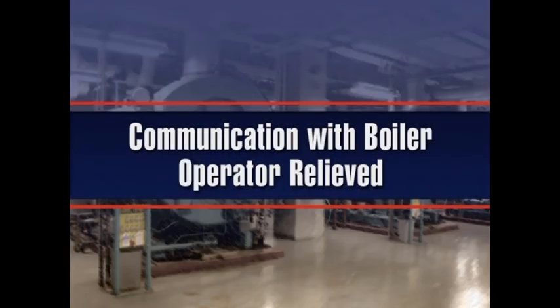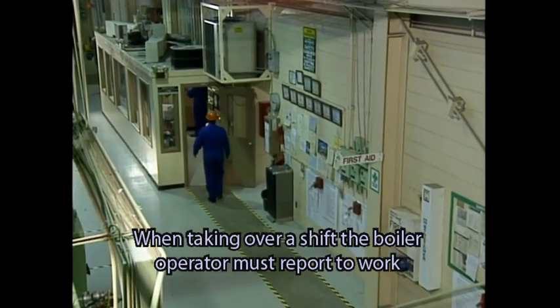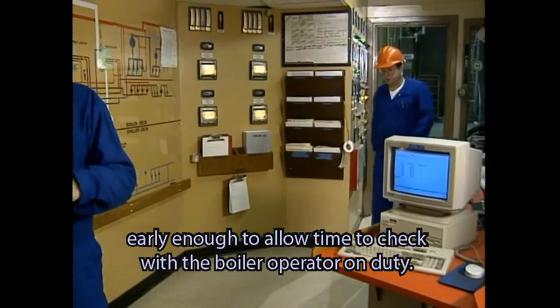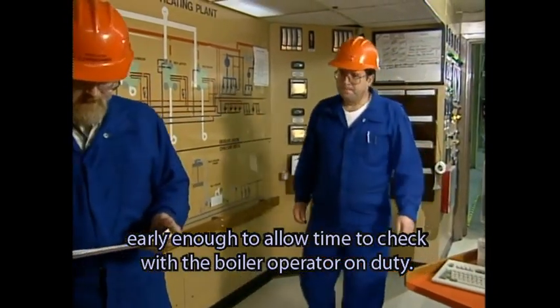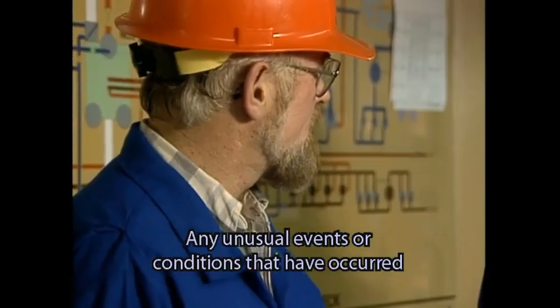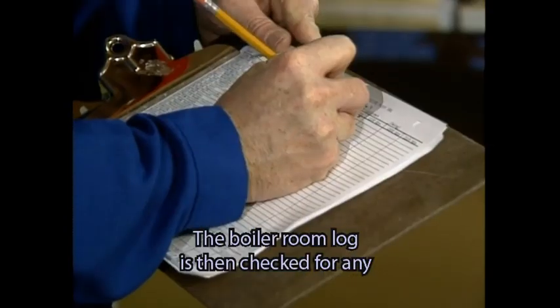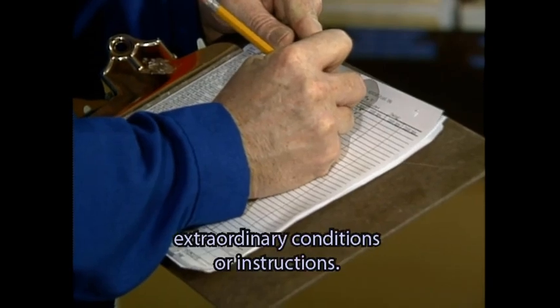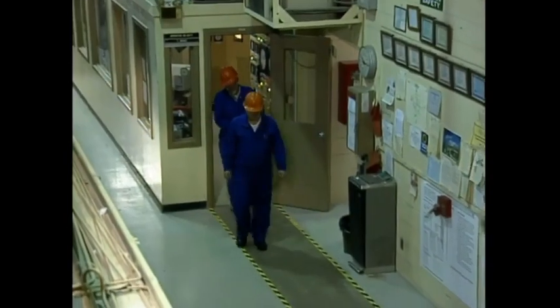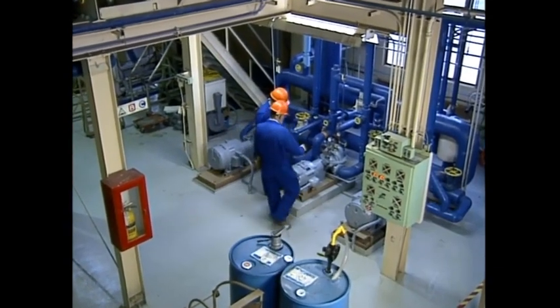Communication with boiler operator relieved. When taking over a shift, the boiler operator must report to work early enough to allow time to check with the boiler operator on duty. Any unusual events or conditions that have occurred during the previous shift are discussed. The boiler room log is then checked for any extraordinary conditions or instructions. A tour of the plant will help identify potential problems.